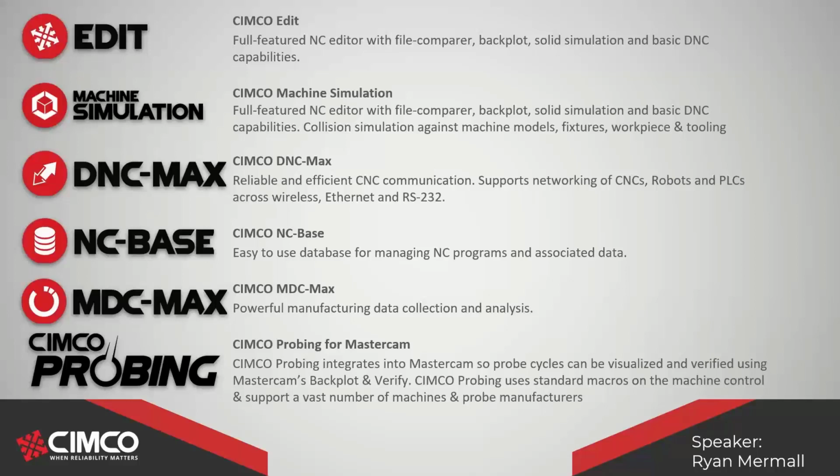And then, to round everything out, is the Cimco Probing, and that's an add-on for Mastercam. That allows you to utilize your machine tool probes to create cycles to set up work datums, in-process inspections, aligning the part to the machine, things of that nature.